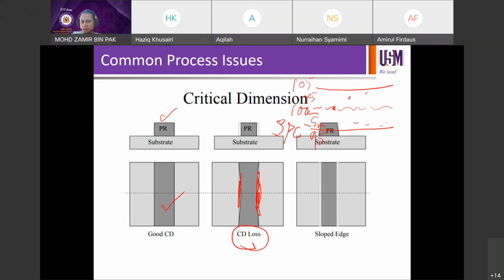And now your CD measured after the ICD is 125. Where is 125 on this chart? Higher. It's higher, right? Simple, right? It's very simple. Up here, higher, guys. So it is called out of spec, OOS. If it's not too far, it's out of control, OOC. There are levels: OOC is out of control, OOS is out of spec. Now your CD has been drifting here and there for a long time, say 3 hours already, and only now you realize. So then you're printing lines.